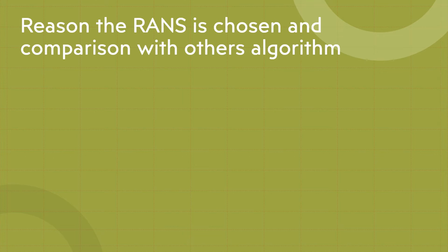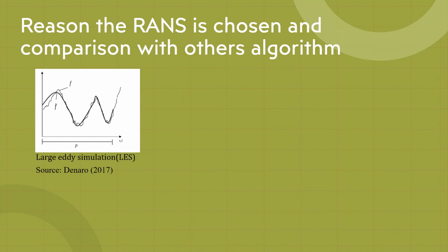And now I'll explain the reason RANS is chosen, and compare RANS with other algorithms. At first I will talk about Large Eddy Simulation. As shown in this graph, Large Eddy Simulation will convert the unsteady turbulence variable to a smoother curve before it is processed for the simulation.